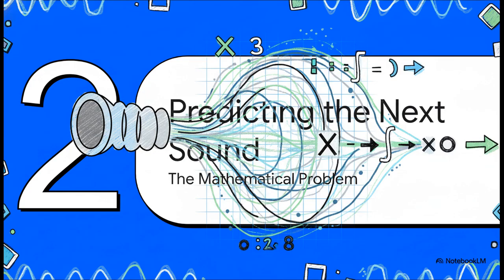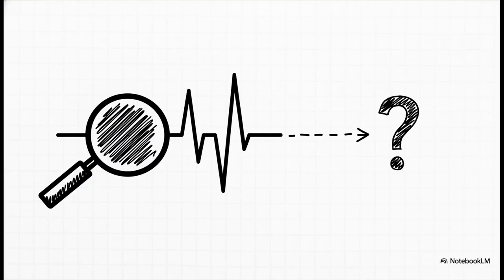Okay, so that physical model's great, but how do we turn it into math that a computer can actually use? This is where the predictive part of linear predictive coding really comes into play. We need a way to describe the shape of that tube using just numbers. And the idea is just so clever. See, human speech isn't random noise. It's super predictable from one moment to the next. LPC totally takes advantage of this. It basically says, hey, we can make a really good guess about the next digital sample of a sound wave just by looking at a few of the samples that came right before it. It's like a prediction game.